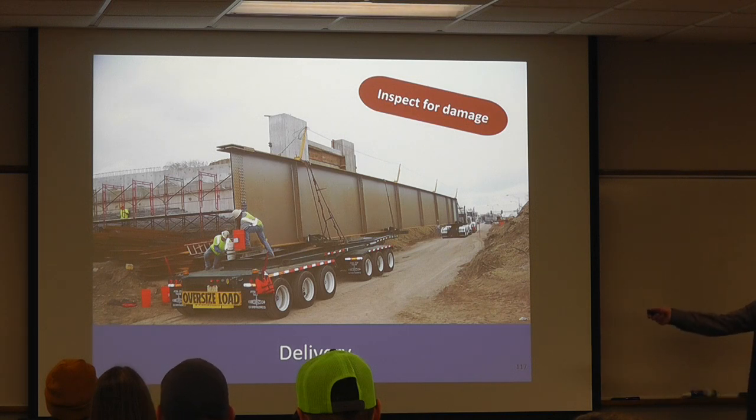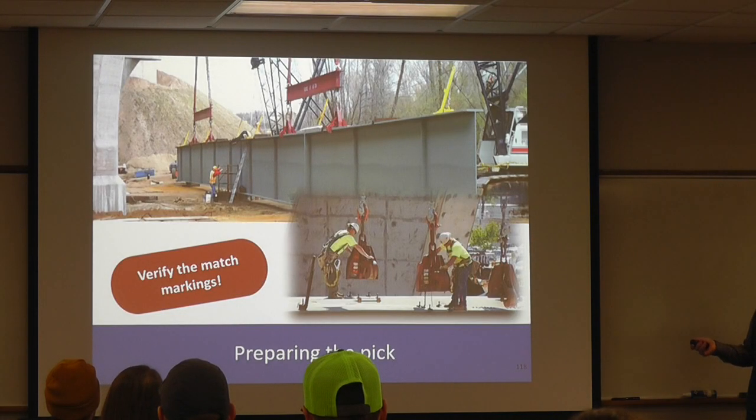You can see here, the contractor's starting to stuff their bolts in one side of the splice. This is a lot of effort. Can be a lot of work to do out of a basket. Oftentimes you can see that their safety lines are installed. This is a time too, if you're savvy about painting the spots for your construction elevations, you can do this while it's on the truck or on the ground, as long as it's safe. So they're going to prep all this on the ground. They're going to get ready for the pick.